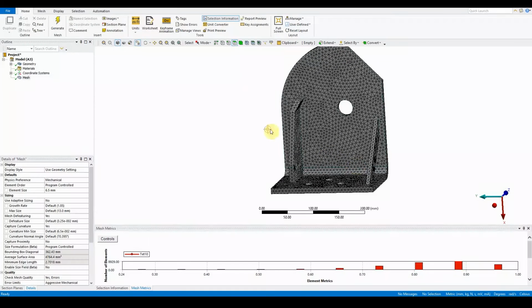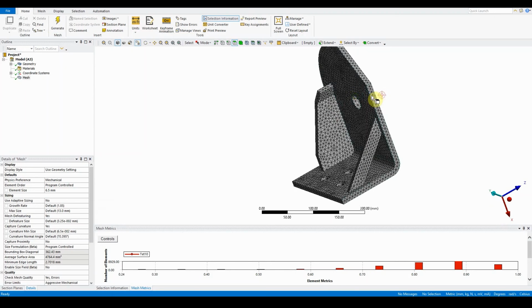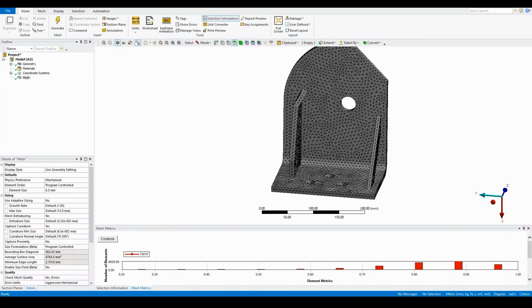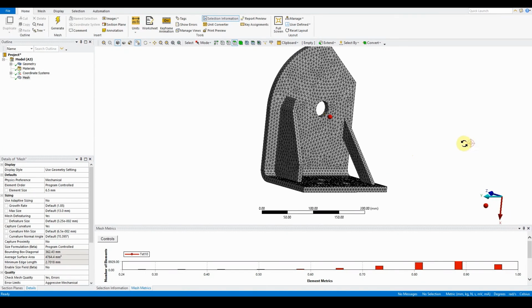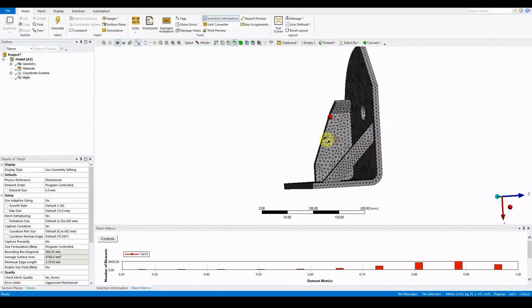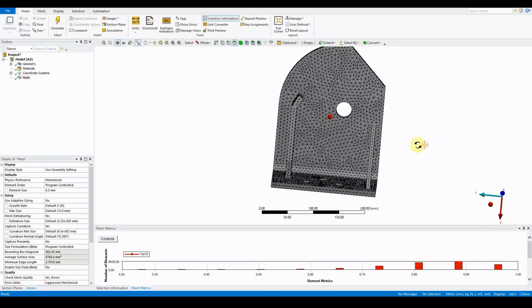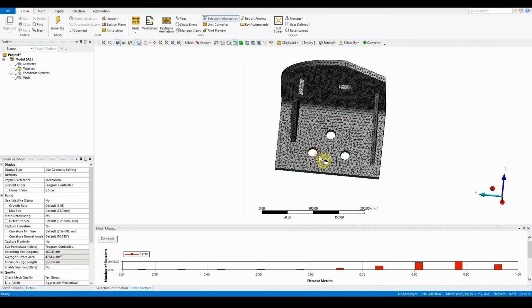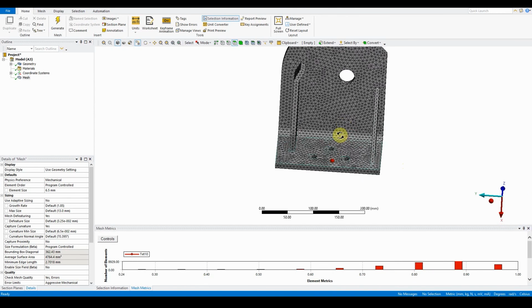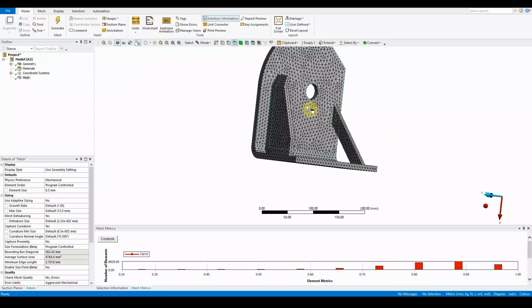Which is really good, but what we want to do is obviously making sure that the element qualities are good everywhere. There's two number of layers going through the actual thickness of the material as well. And that's very simple in terms of this workshop. Again, you could emphasize a lot more clarity on these key elements, but this will be looking at using local mesh sizing, which is the next workshop package.